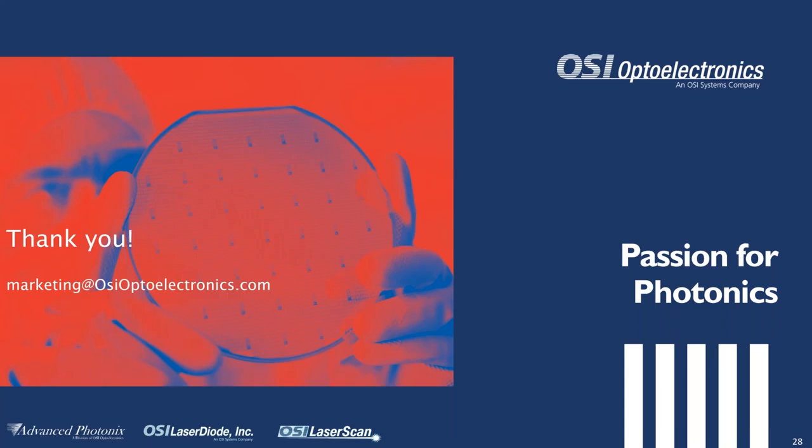As for any APD, we have to apply some quenching circuits, and the best way to do it is either to use, for example, passive quenching with a quenching resistor connected in series with the photodiode, or, in many cases, when people are measuring light within a large dynamic range, it's very practical to bias the APD in a pulsed mode, when you apply the reverse bias only when you expect the optical quanta to arrive.